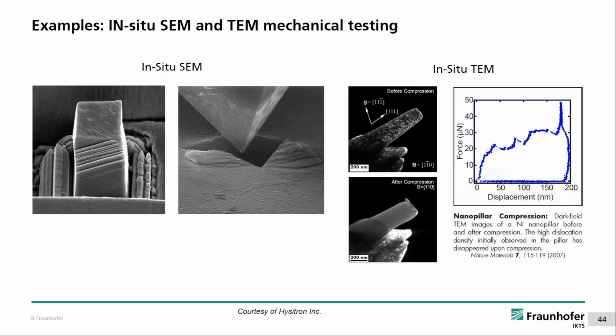Then depending on the shape of the particle, if it's a ball-shaped particle, there are analytical solutions to calculate the stress and strain at the moment of failure. If it's a non-spherical shape, you have to use finite element solutions to get the stress and strain at the moment of fracture or plasticity, and then you can get information on the strength of the particles and the materials.